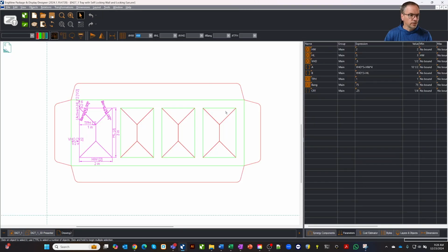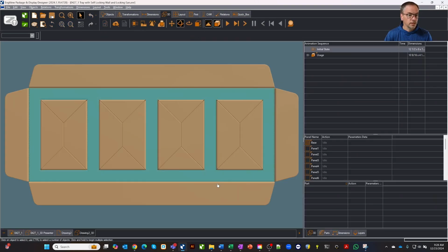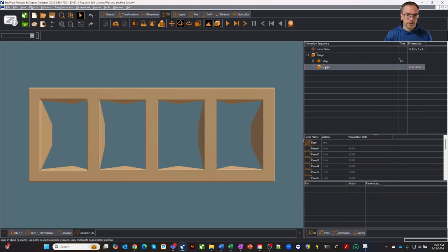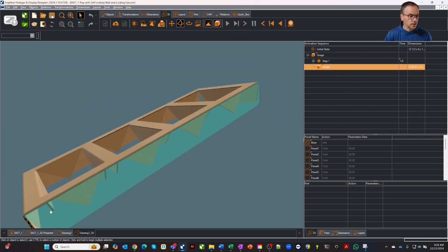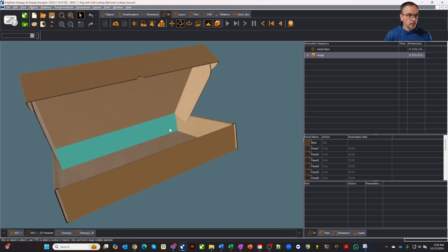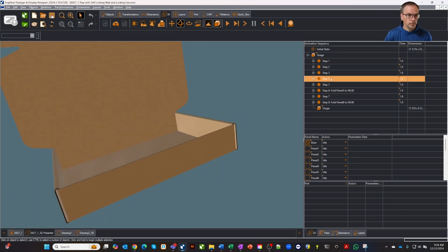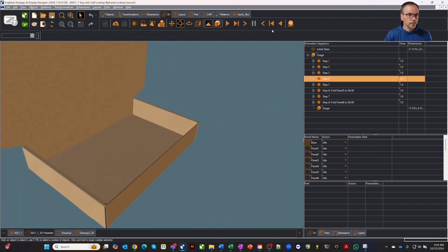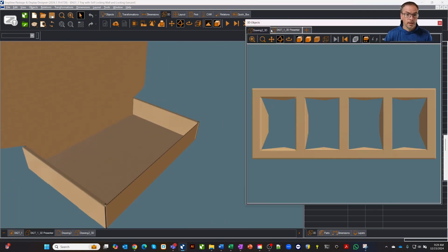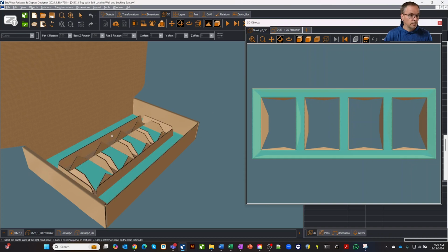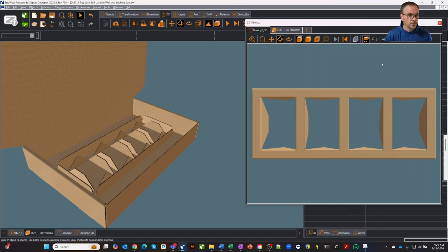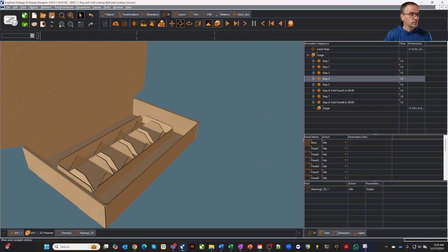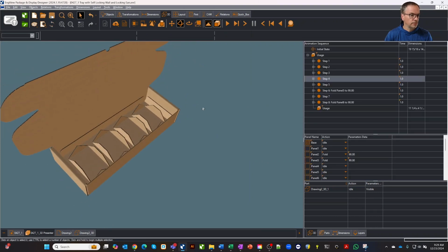Let's come back over to this drawing and create a 3D out of it. We'll say 3D, create 3D. Notice it just folds everything real quick up to 90 degrees, which is great. We now have a 3D. Let's open this box up to a point like here where we can stick it into place. I'll grab that new 3D part, drop it in the box, and center it up. I need to refresh the 3D so you see it'll now fit in there.